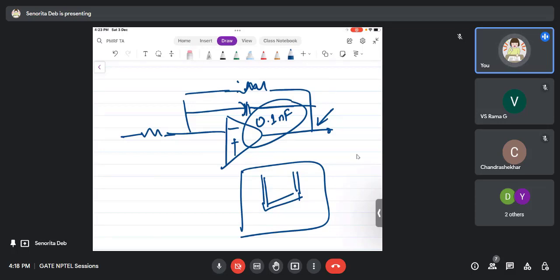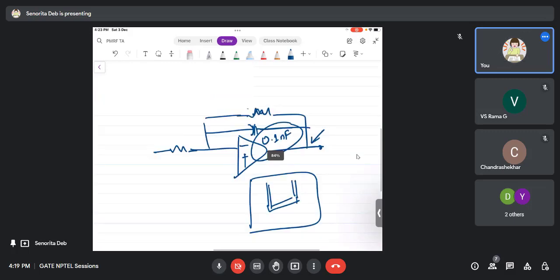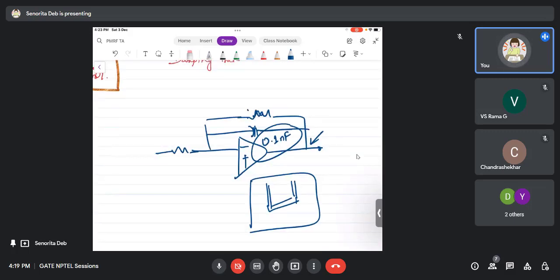Those high frequency oscillations normally come from power supply noise, and the power supply noise is nothing but the noise from the PCB tracks, and the supply from wherever you are taking. So even if your supply is regulated, the PCB tracks add up to the noise, and therefore these kind of caps are used in feedback, with your feedback resistors or something, to cause those kind of actions. Okay, but if those capacitor values are not carefully monitored, they cannot aid stability. They can also cause oscillations.